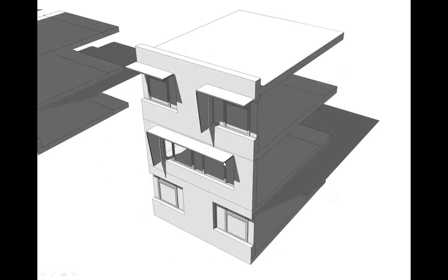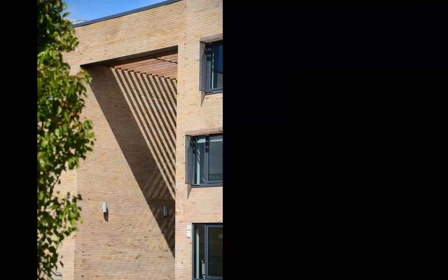We then moved on to this device, which, as you can see, is shading the high sun in the south, and we've got this extra panel which is trying to shade that difficult west sun. And we have no shading on the east, because that eastern sun is not so much of a problem. And that's the actual built project. So that's that side panel, and in the end we had these timber louvers shading the top of the window.